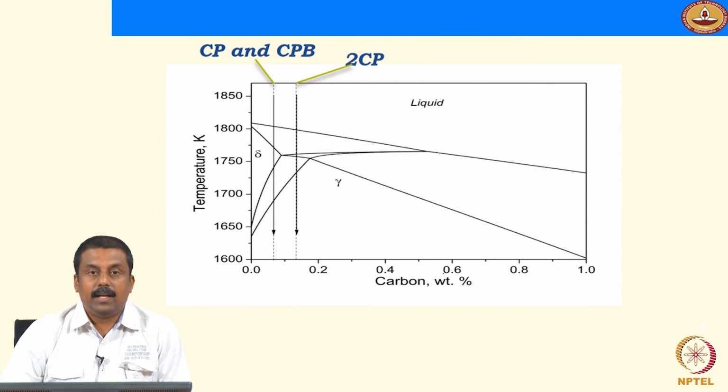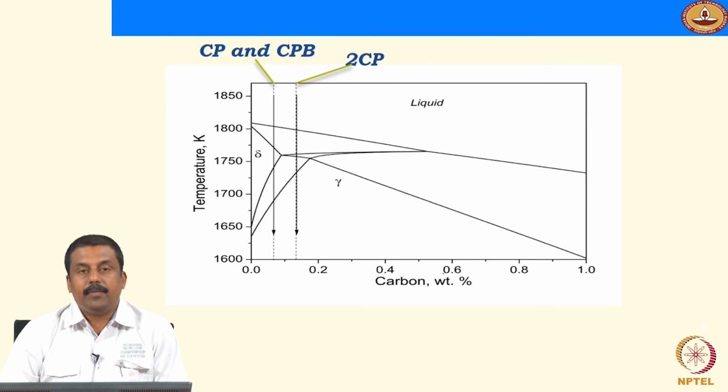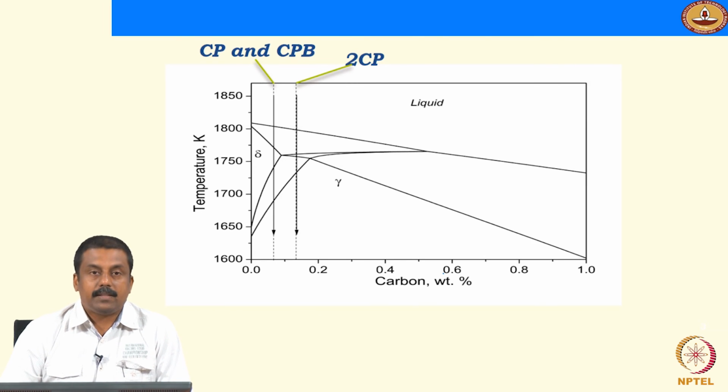The first understanding we have to make when we want to understand the elemental behavior is the solidification mode, how the weld pool solidifies. When you cool a weld pool to room temperature, the mode of solidification is extremely important, because that is going to determine the segregation behavior of the alloying elements, especially the alloying elements which partition towards liquid.